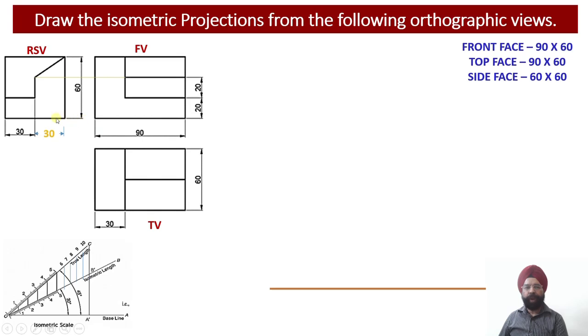That is, there is a bottom block which I can observe over here. This is the bottom block of this particular solid, which is nothing but a rectangular component. So I can see even from the front view, in this block, this is the flatter portion of the block. Please check, this is the flatter portion of the block, and then there is this vertical portion of the block. So in this first element, I will be drawing one ring which will be at a distance of 20 millimeter. So this will be defining my first element or the base element of this solid. So this is going to be my first element.